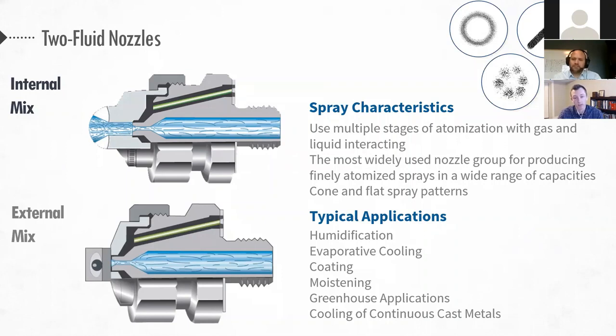Similarly, if you set your liquid, you can then choose to increase your gas to maybe increase your atomization or something. And you can effectively control drop size that way. So let's say you need a smaller drop for some reason, you have that capability of adjustment.